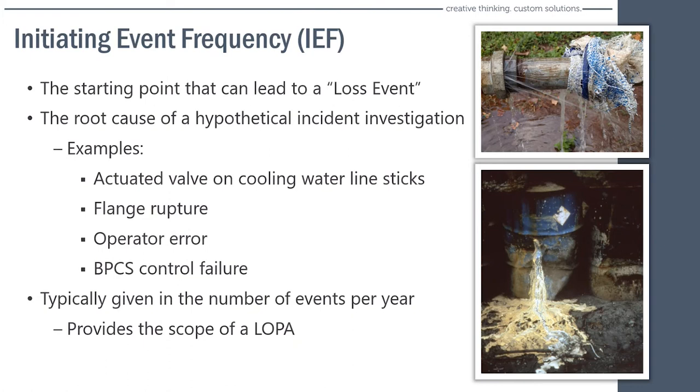Well, let's go back to our simple example. Say that we're filling that acetone tank, as I mentioned, every shift, and you're running 3 shifts a day. So that's 3 times a day that tank gets filled, probably by 3 separate operators, because you're also on a shift schedule. If you run for a year, and we'll use simple math, say 333 days a year, now you have 3 times 333, you're at roughly 1,000 events. So you have 1,000 events a year where you could overfill that tank.